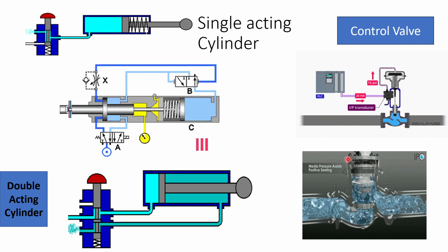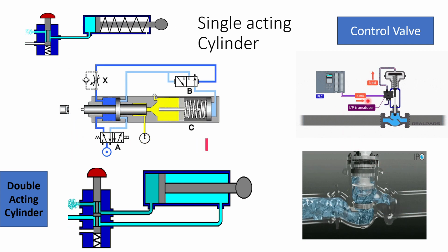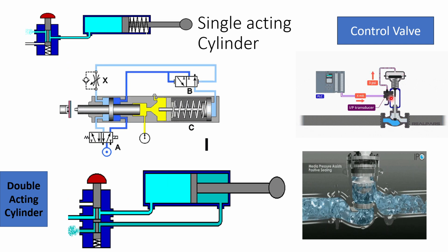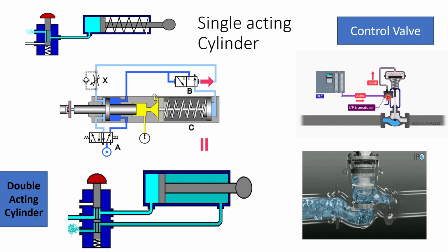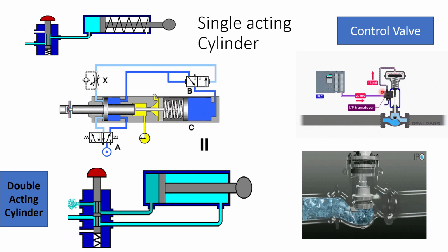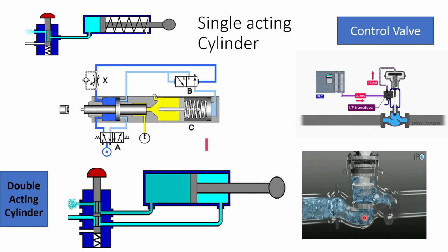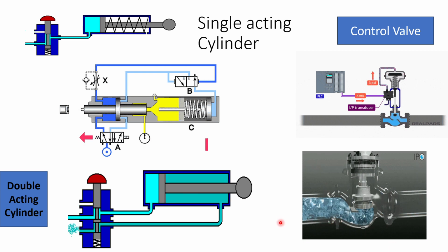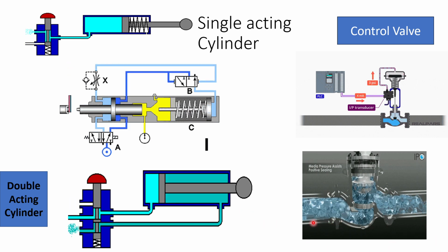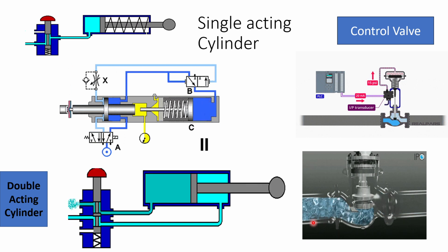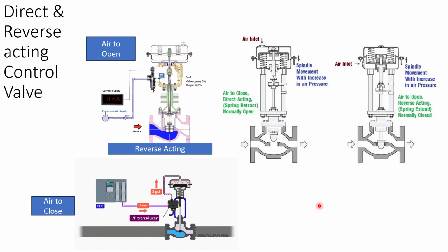Same thing on the right side, you are able to see how it is happening in a control valve, and this is the single axis. So you see a 4 to 20 milliamp signal is coming and it is going to the I to P converter, and when the orifice is closed, it is 3 psi. At 3 psi the valve is opening, and at 15 psi full air flow the valve is closing. This bottom one is showing how the valve opens and closes, and when the valve is closed, there is no flow. When the valve opens, the flow takes place.